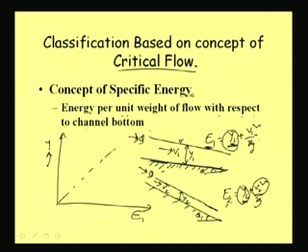So this is y plus v square by twice g. If I plot E versus y, a line, then say this is a 45-degree line, and we always have a positive term, v square will always be a positive term. So total energy will always be on the right side of this 45-degree line, because this line represents E equal to y. Something more than that means it will always be on the right side, and then if we draw a line, it will be like this.